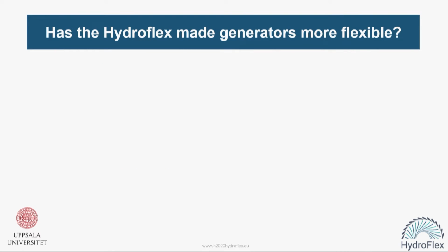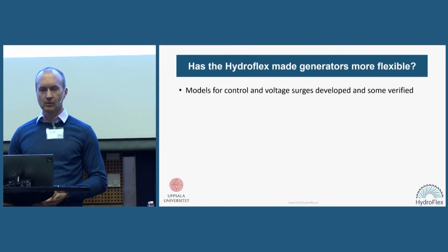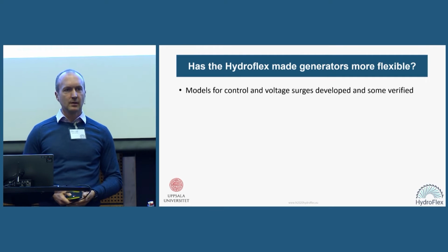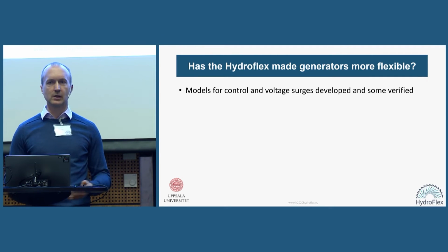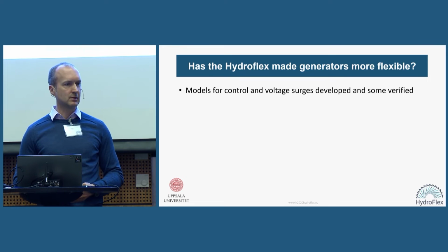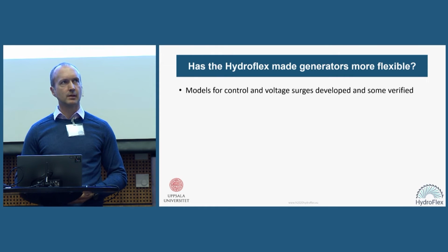So if we were to answer this question, has the Hydroflex project made generators more flexible? What can you say? Well, I think the modeling for control and also the voltage dips, the low voltage ride-through, has been simulated at the University of Strathclyde. We've seen that we can achieve better performance with the full power converter and better control there. Models have been developed, and the trade-offs are not so big and the benefits are there for sure.